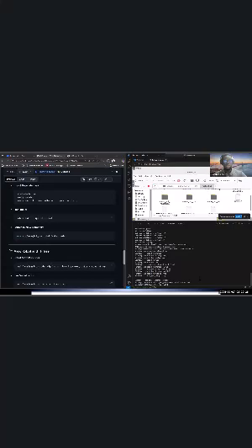So what does this mean? When you run source install slash setup dot bash, it means you've initialized ROS. So ROS should be active in this environment. Very important: if you call build, then you source. It means you're sourcing the workspace. What's the source for the workspace? ROS, the ROS2 onboard.